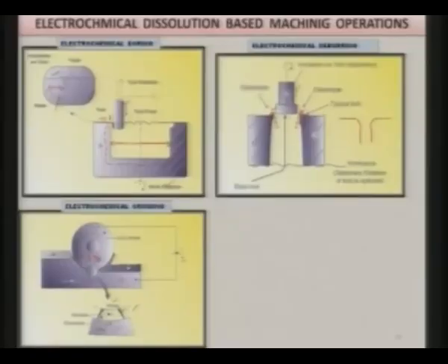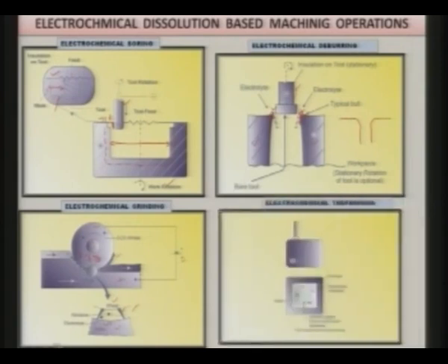So, here material is removed by both the processes, and this will improve the surface finish of the machined component. When it goes to zone 3, whatever burrs or irregularities are created due to the grinding operation will be dissolved in zone 3, because there only electrochemical dissolution is taking place. Whatever irregularities are created are sharp, their current density will be higher, and that is why they will be dissolved first rather than the rest of the part. So, from that point of view, this process is very good.